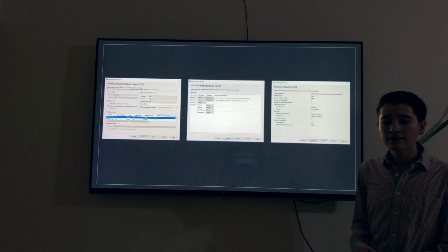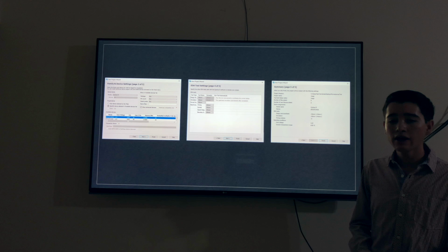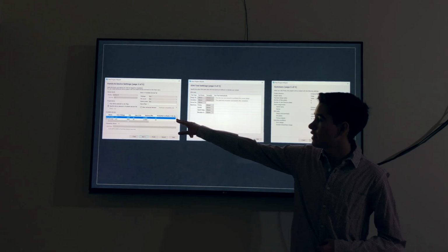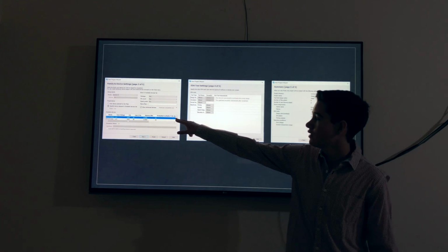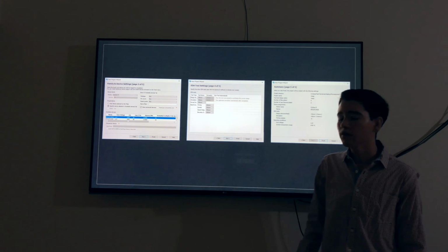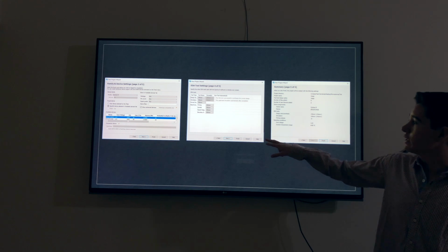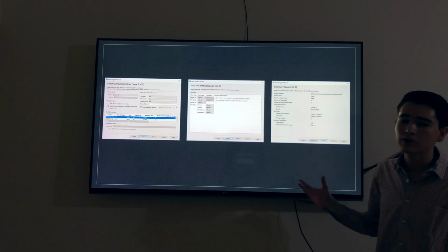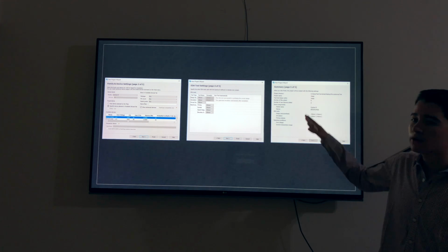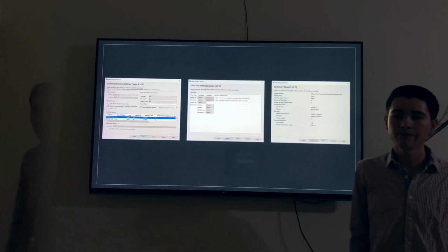Then it asks us for the device that we are going to use. We are going to select the Cyclone II, the EP2C5T144C8 model, and we click Next. Next we click Next again because we don't need this window, and this is the summary of our project, so we click Finish to continue.